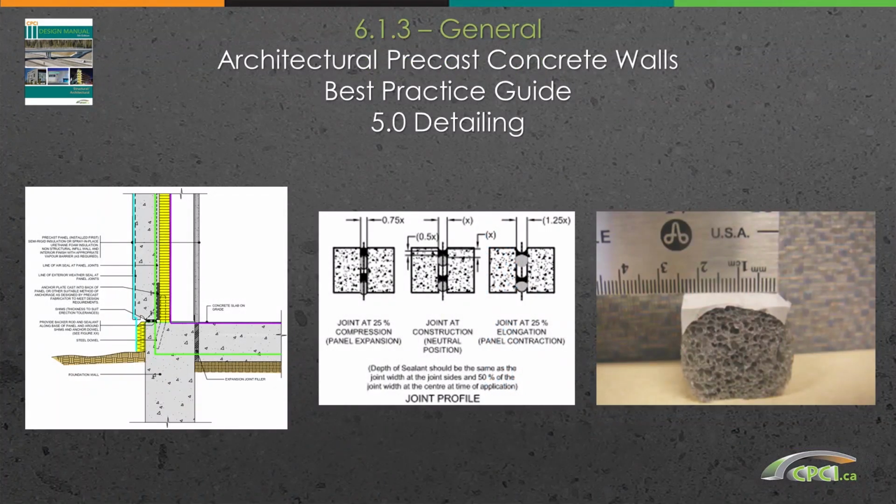Chapter 5 of this new reference guide discusses how one of the critical links to a weatherproof building envelope is the joint design and the selection and use of sealants and membranes to ensure that continuity between similar and dissimilar building materials exists. The design and execution of these joints is extremely important and must be accomplished in both a constructible and economical manner. Selecting the right product, appropriate joint design, proper surface preparation, and correct application technique will ensure the joint and sealant provide the desired performance, design service life, and pleasing long-term aesthetics.